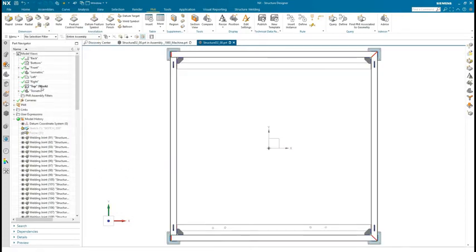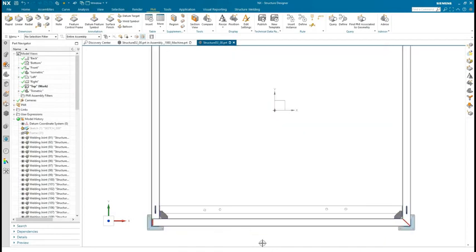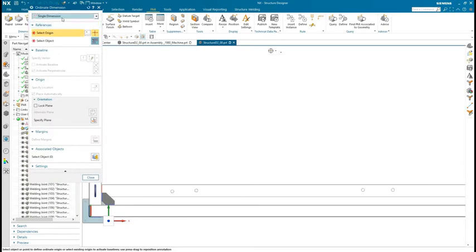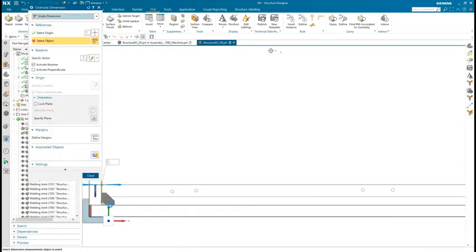You can add linear, radial, angle, and hole callouts. Geometric tolerancing can also be included, such as datums and feature control frames, as well as surface finish symbols. Have a look at the rich command set on the main toolbar. You can also add weld symbols, but since those were automatically added during the weld definition process, we get those for free.